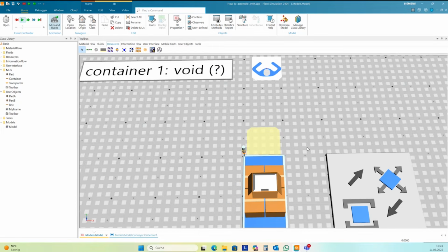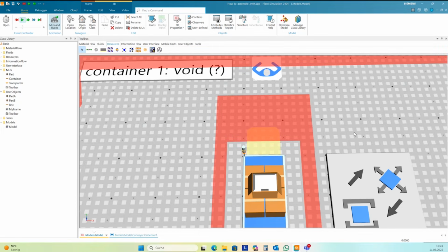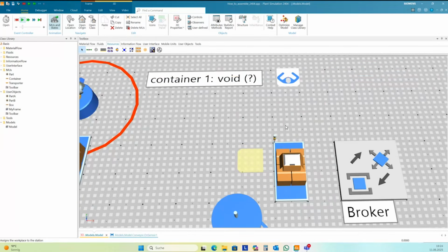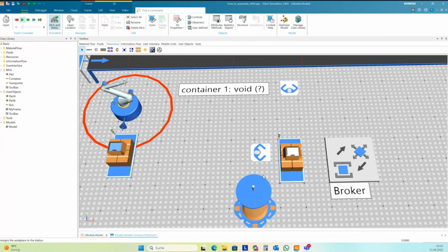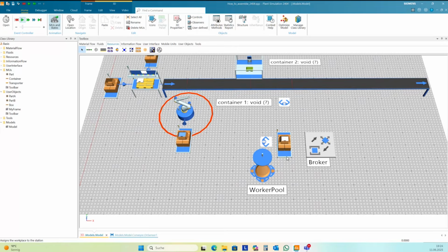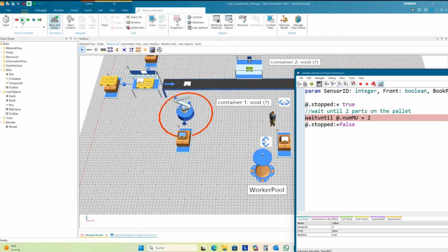Yes. Okay, you can check this with O, and okay, it wants to be located here. It's inside of a buried area, and so the worker cannot reach this. Next try. Okay. And now here the worker is going here, but moves the part at the start of the conveyor, and this is totally wrong, this behavior, and so we need to change this.